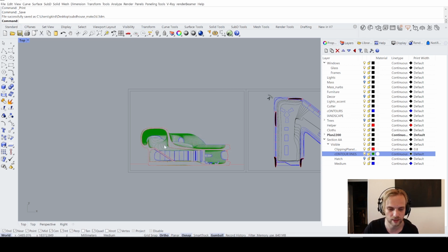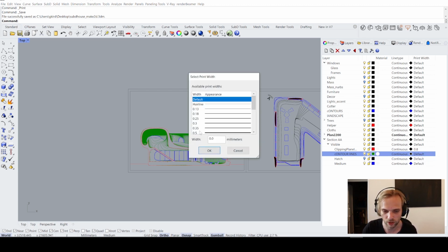And if that doesn't look good, then I will have the option to switch it back to dark gray. For the thickness, I will do 0.09 millimeters. I did some tests with my printer, and it seems like anything lower than 0.09 millimeters on my particular printer will not print properly. So 0.09 millimeters for me is the thinnest I can go.